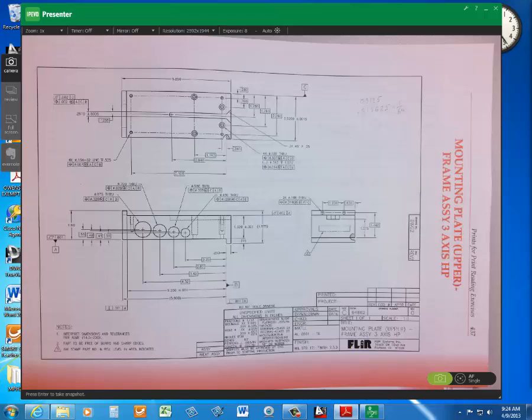All right, so with that in mind, the counterbore produced at 0.312 MMC, its position tolerance is, Lewis? It's right next to the little circle M for the counterbore.